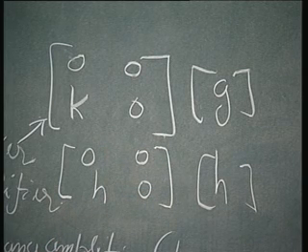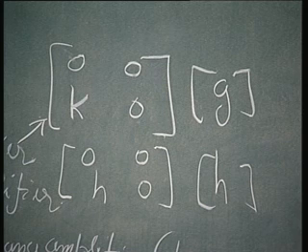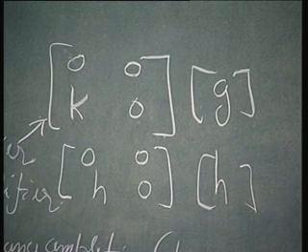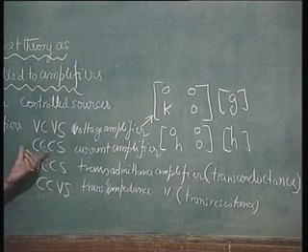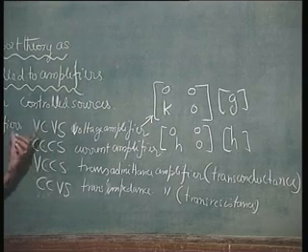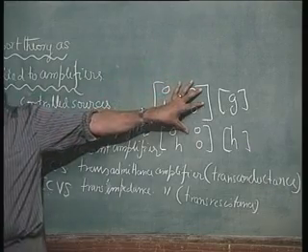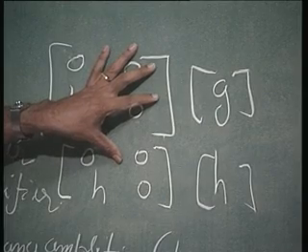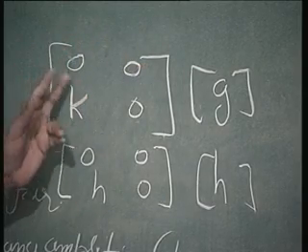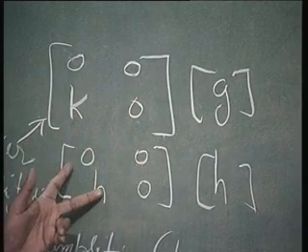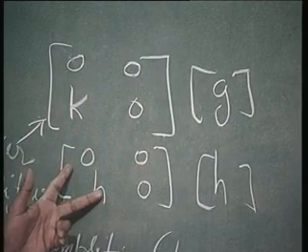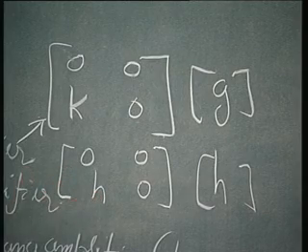I mean, you can represent a non-ideal amplifier by any one of the four. But once you recognize the source impedance and load impedance, you will recognize that particular thing as a particular amplifier, and therefore you must adopt the proper parameter for analysis. Then you would know the magnitude of these. These will go towards 0, and this is the only parameter which is going to be realistically large.